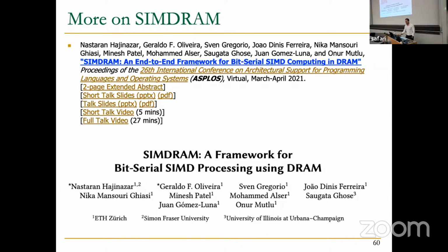And also, is there a limit to the size of the program that we can execute? Because the subarray has a limited size. Yes. And is there support for using multiple subarrays and moving data between subarrays? Not in this work here. For all of those operations, the data fits or can be partitioned in a way that you don't need to move the data across the different DRAM subarrays. But we discussed in the lecture this LISA paper, which connects the subarrays using some isolation transistors. And we can move the data using that approach, for example, if you need to move data from one subarray to another one because it may not fit.